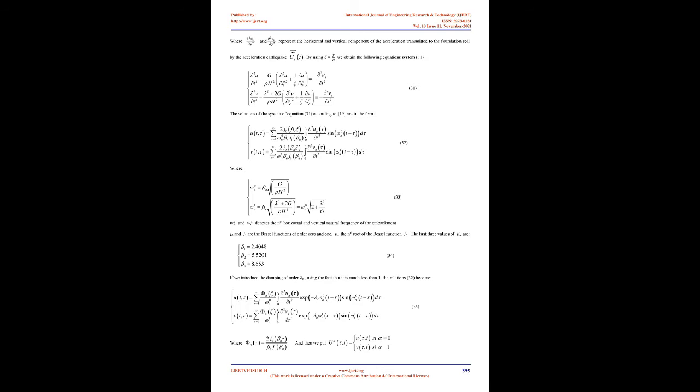If the factor equals 1, the unstable part, P, of the embankment, figure 3, does not move, or is stable. If it is less than 1, the unstable part, P, of the dam, figure 3, moves along the failure surface. This displacement must be estimated in order to compare it to the values of the admissible displacements tolerated by the project owner.